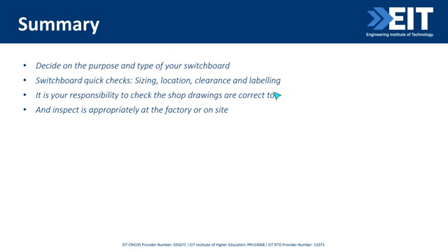If you're designing a switchboard, it is your responsibility to also check that the shop drawings are correct, so what you're getting matches what you were intending. And lastly, if it's possible, check what's being constructed after the fact to again make sure everything's been carried through correctly from design through to build through to installation.